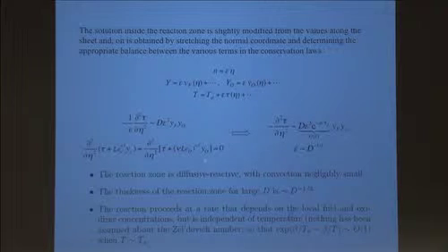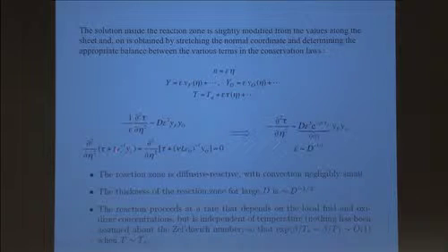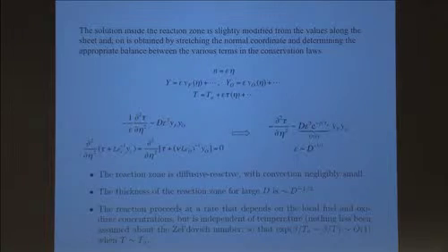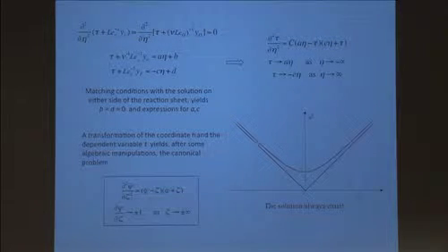And these are the coupling functions. So if you solve these equations first, because they are simple, they are equal to 0, then you can find the relation between YF and tau and YO and tau. And if you put it together, you're going to get a single equation for tau that has YF and YO. So you see YF and YO are related to tau by a linear function, if you like.